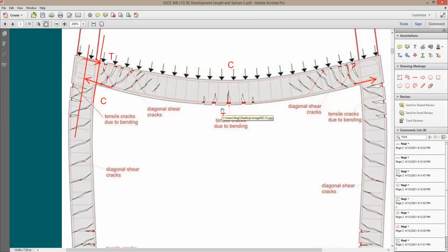Okay, from Jacob, he says it's going to be at the face of the column. This is correct. At the face of the column, this is why I have here the maximum moment. Because once you get through the column, the depth of this structure is going to be the entire column height. So it doesn't count. So I'm going to say this is going to be the support itself. I'm going to take it at face of support.